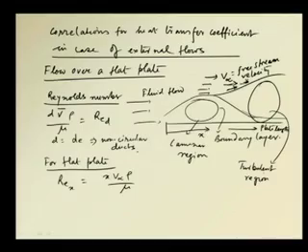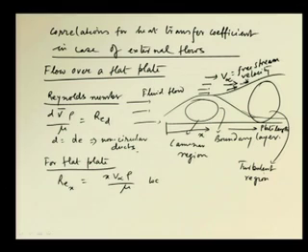One important thing here is that even though the free stream velocity remains constant, where the effect of the wall is not there, the Reynolds number is a variable quantity with respect to length from the leading edge. Because the Reynolds number is a function of x, where x is the coordinate at any particular location of the plate, it is also called the local Reynolds number.